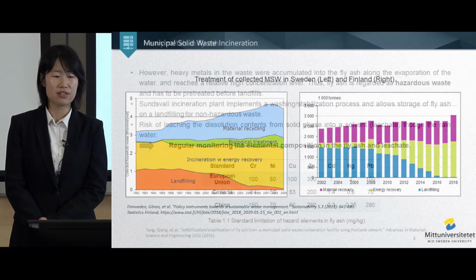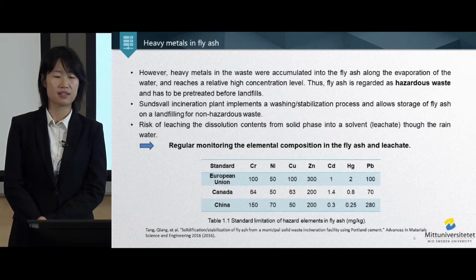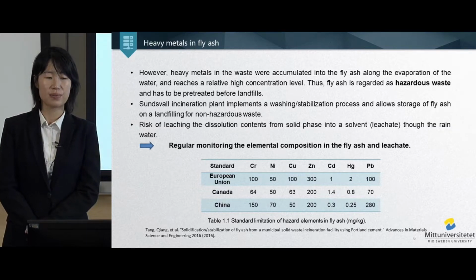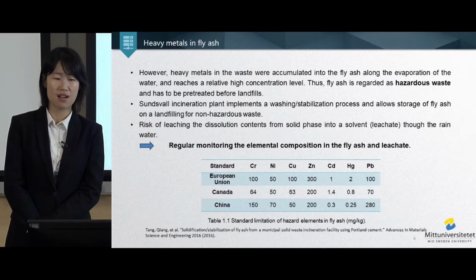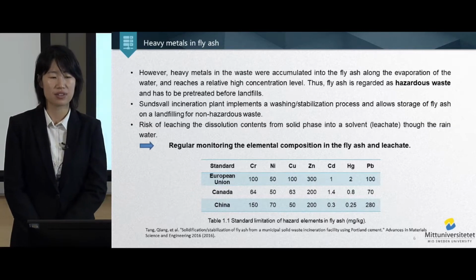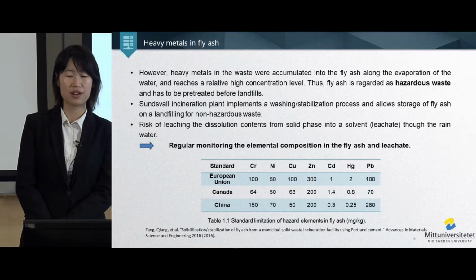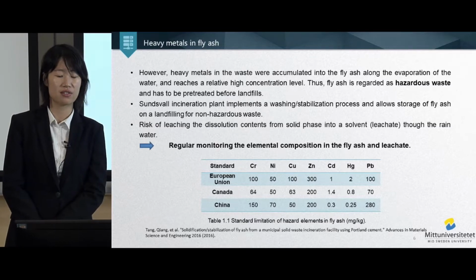However, heavy metals in the waste are accumulated into the fly ash and reach a high concentration level in the end. So fly ash is regarded as hazardous waste and has to be pre-treated before landfilling. Sundsvall incineration plant implements a washing process that allows storage of fly ash on landfill for non-hazardous waste. The washing process generates a mixture of fly ash and sludge that has low leaching of metal content to the